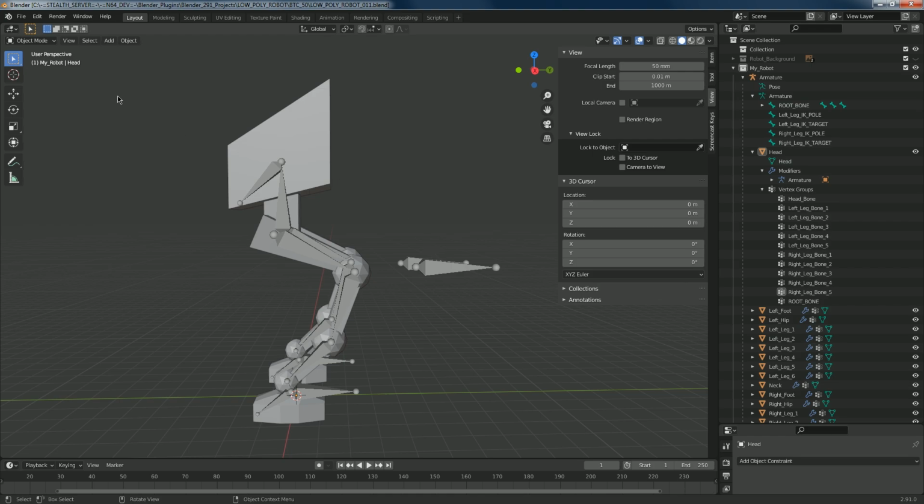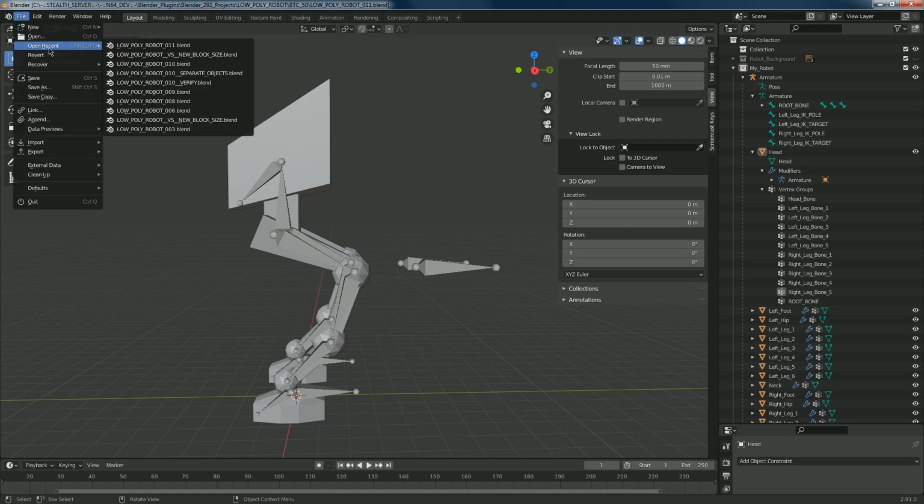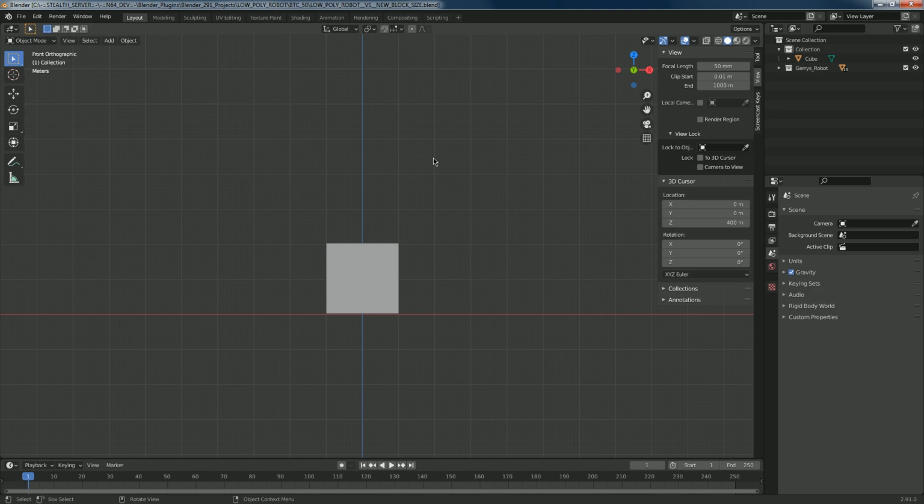So first, before we do that, I'm just going to open up this sample project just so you can have an idea of the actual scale size. So when you create a little cube here in Blender, it's usually about 2 meters in height. So if we put our 3D cursor here, you can see under view for 3D cursor, the Z-axis here is measuring about 2.0 meters from the world origin point. So that's the height of a new cube that we placed in the scene.